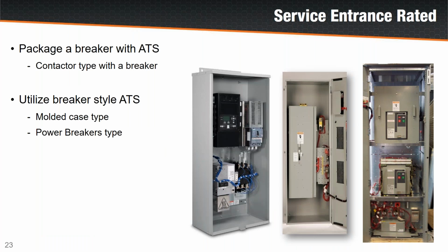Service entrance rated switches can be implemented using different technologies. Kind of the premium way to do it is a contactor paired with a breaker, which is shown on the switch on the left, or it can be implemented with two circuit breakers. So different implementations for service entrance rated.